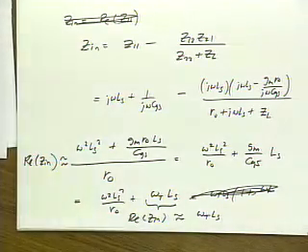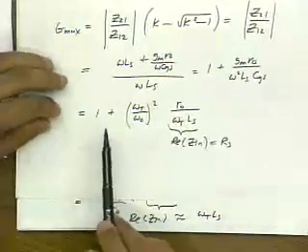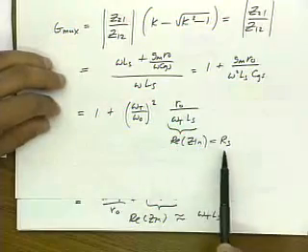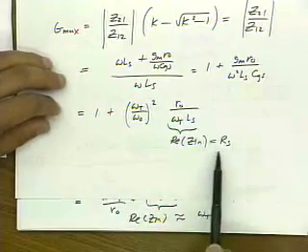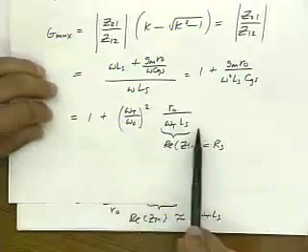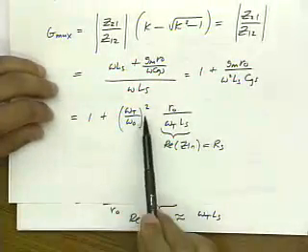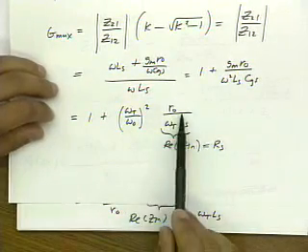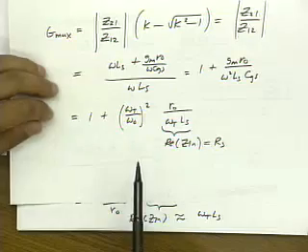Now, we'll look back to the equation we derived here. Here, I said that this is approximately the real part of Zin, which for an impedance match condition is just Rs. And so now you see that the power gain is proportional to omega T over omega naught squared times the ratio of the output resistance to Rs. Okay?